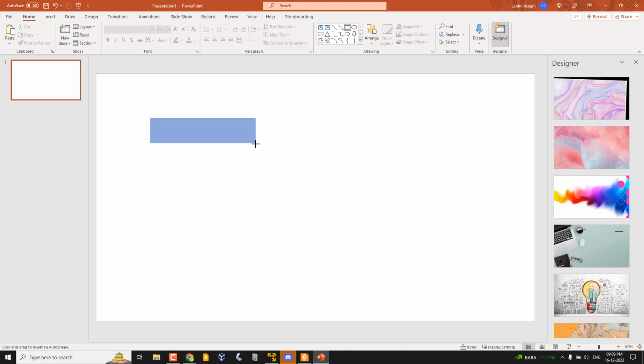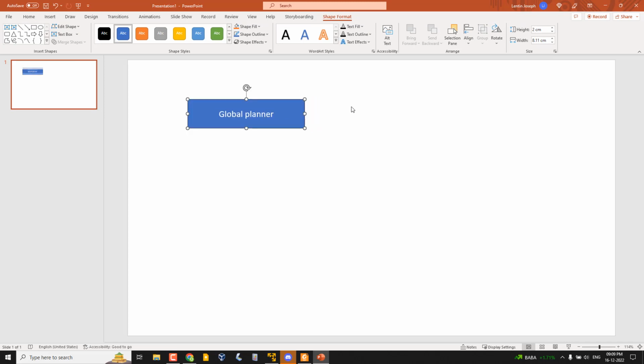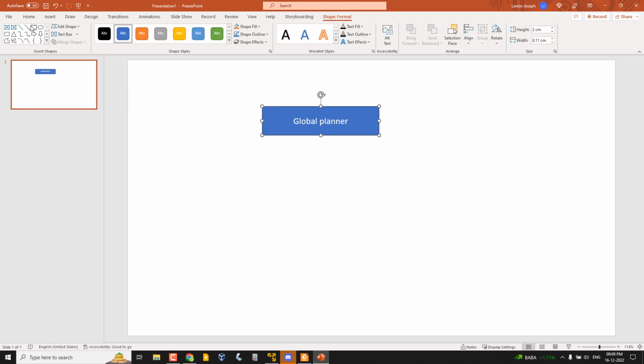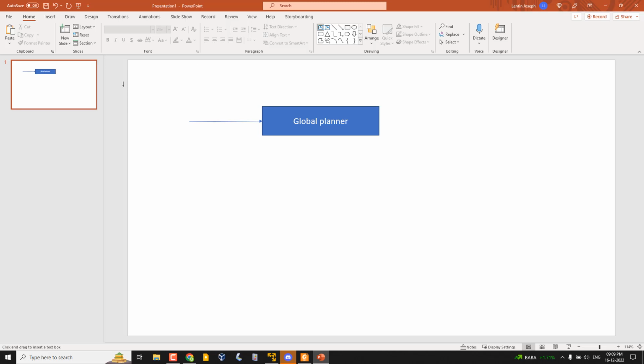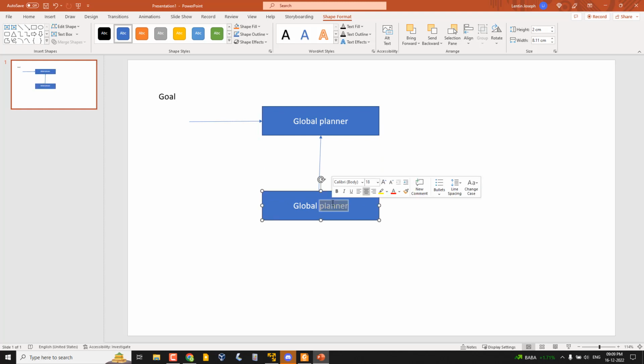So we have the global planner. The input of this global planner is the goal position. We have the goal position, and the global planner has the cost map, that is the global cost map, and the global planner can give you a path.